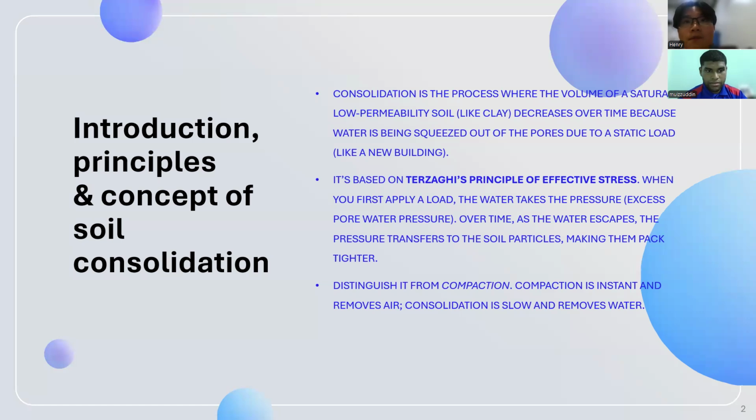When you first apply a load, the water takes the pressure, the excess pore water pressure. Over time, as the water escapes, the pressure transfers to the soil particles, making them pack tighter. And also it is distinguished from compression. Compression is instant and removes air, while consolidation is slow and removes water.